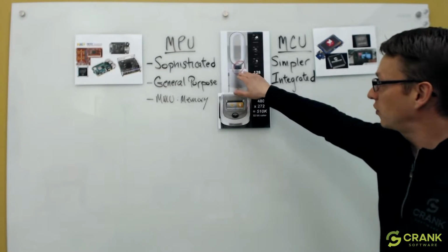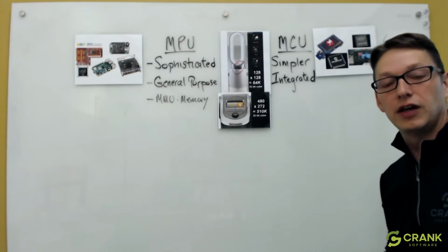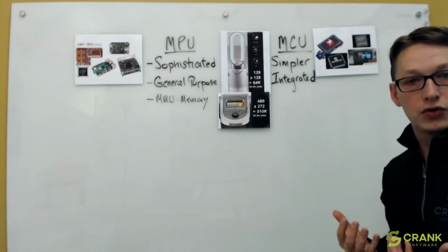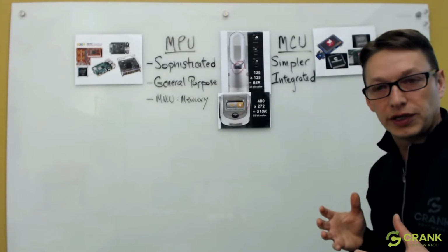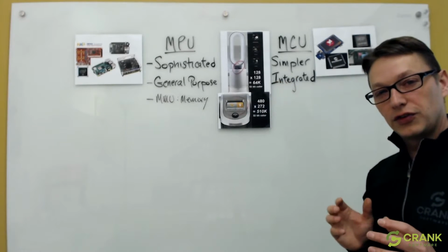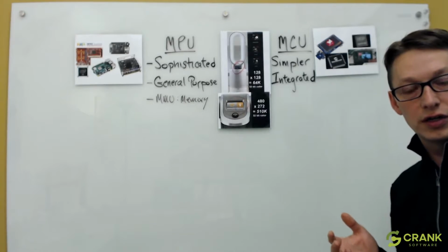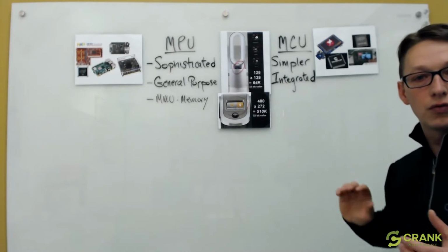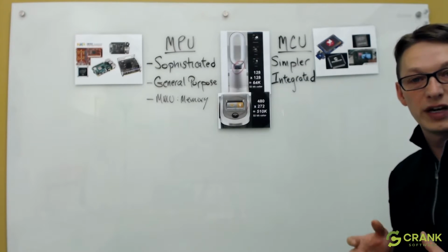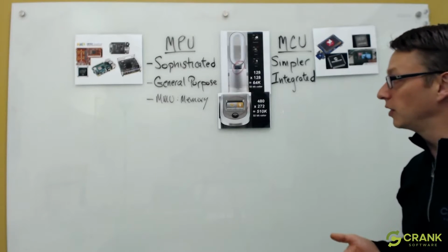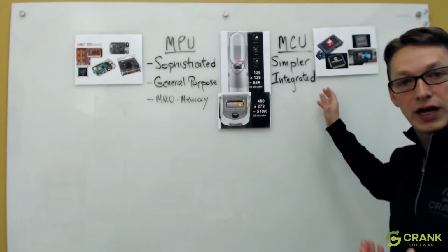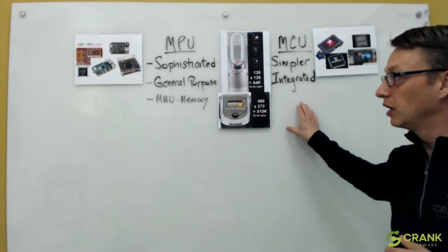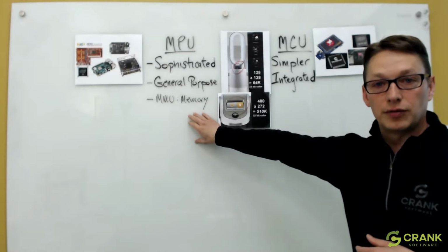And so if we were to take this tiny little display here, it might be a little difficult to see through the web interaction here, but let's assume that it's 128 by 128 pixels, a relatively small display. That display, if it was using a full 32-bit color, full red, green, blue, alpha channels, would use roughly 64K of RAM, right? That needs to be available to the system. And if you were a simple system and you don't have integrated memory, that's a big chunk to pull out of your chip's core. So this is why it's typically in the realm of MPUs.